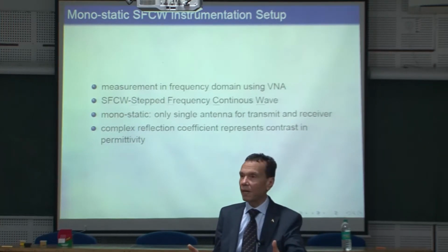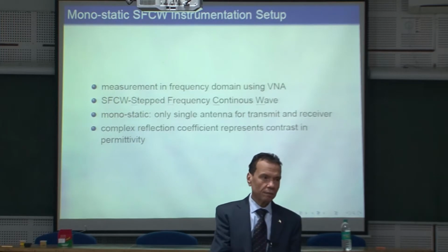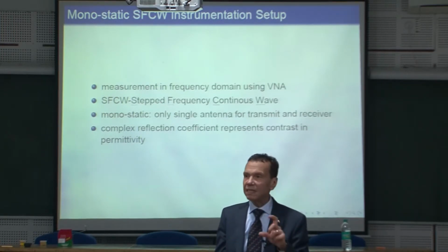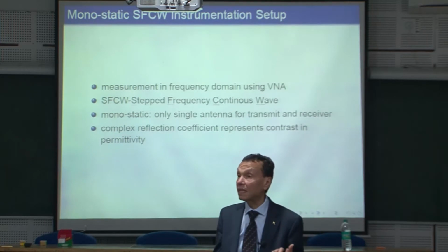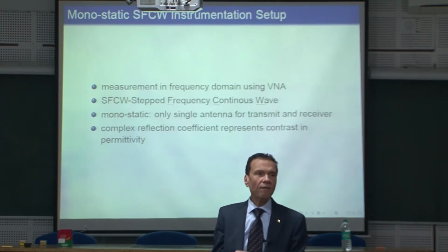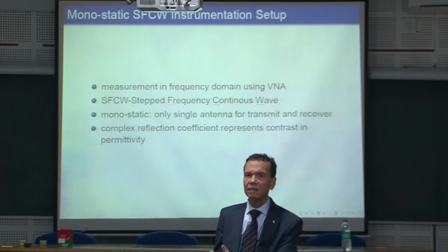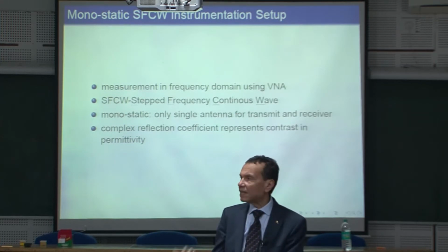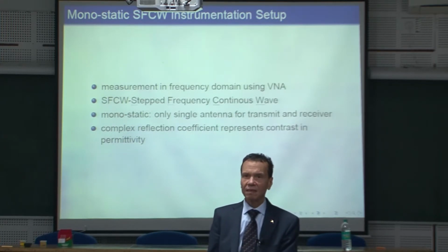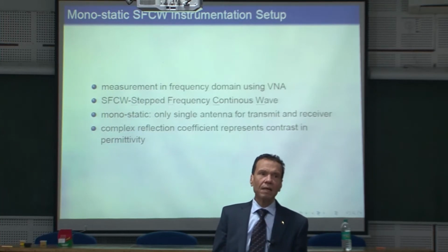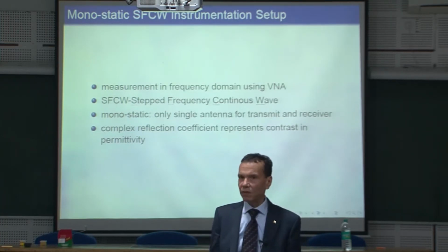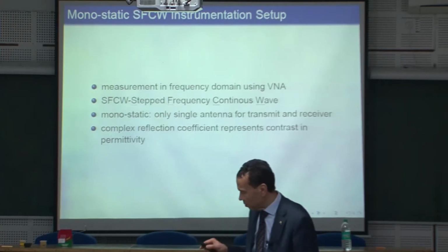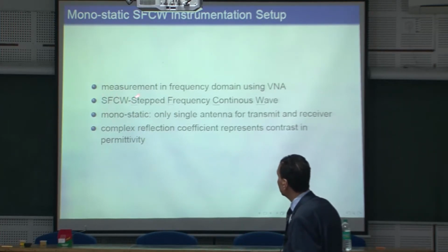So you can also have a short pulse, inject or insert high power, but this short pulse suffers from not the same signal to noise ratio and also not the same dynamic range as stepped frequency. For laboratory purposes, this is okay because you don't insert in your research the time factor. I would like to work fast. I can work now in order to have the best situation, and then I can move afterwards to the other one. This is what is called a stepped frequency continuous wave.